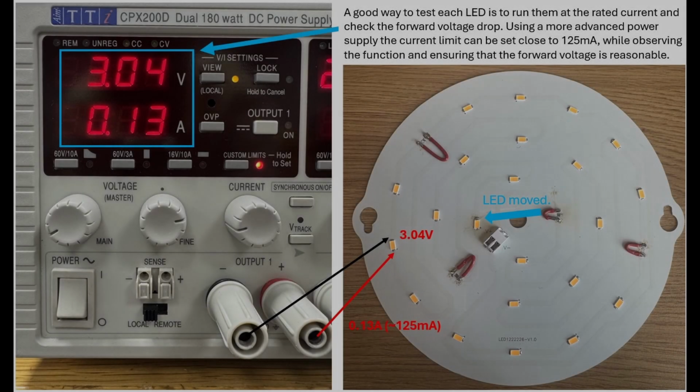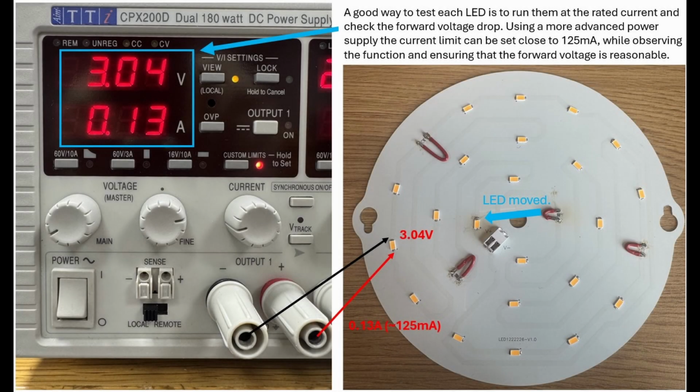So what I realized I had to do was check each LED, even if it lights up, and see whether it is a good device. Does it work according to the datasheet? I don't have the datasheet, but since I have 26 LEDs, if most of them operate in the same way, I can assume that they operate correctly, and any LED that sticks out probably has something wrong with it and should be replaced.